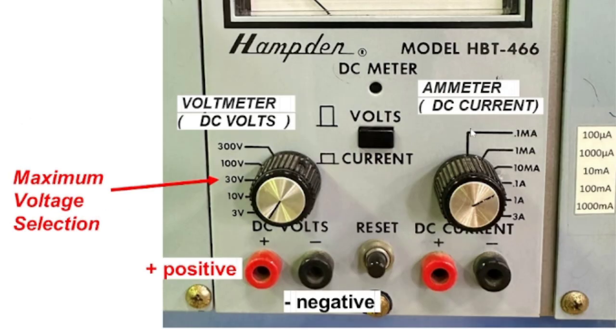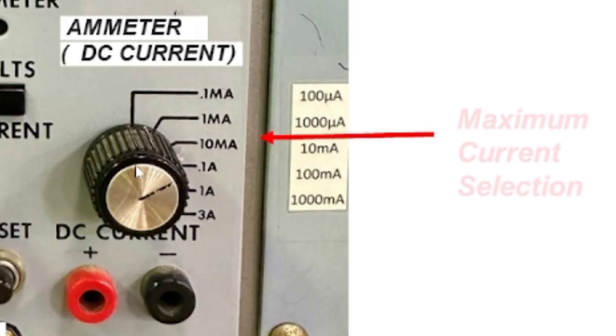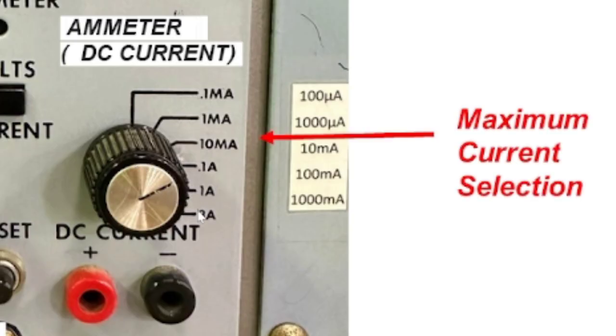Now, on the right side, you will see the ammeter, which can measure the DC current. And there is a selection here where you can choose between 3 amperes, 1 ampere, 0.1 ampere, 10 milliampere. I think there's a mistake here. This should be a small letter. This is not really mega. So just take note that this 10 mA here represents 10 milliamperes only, not mega. And then we have 1 milliampere here and another 0.1 milliampere.